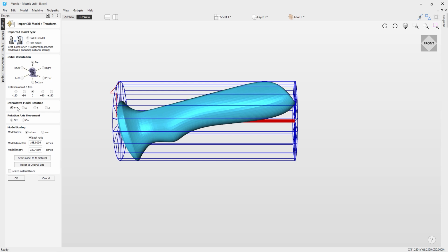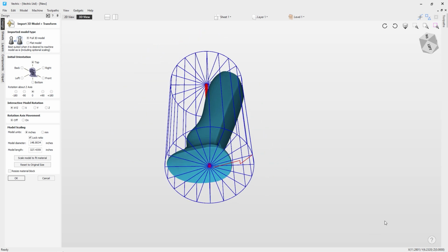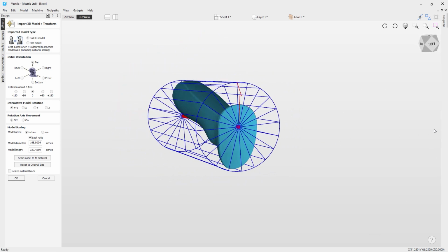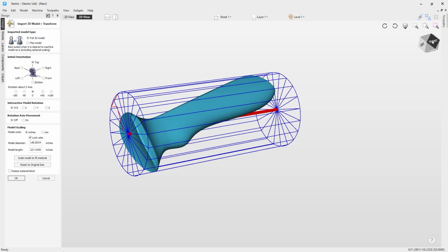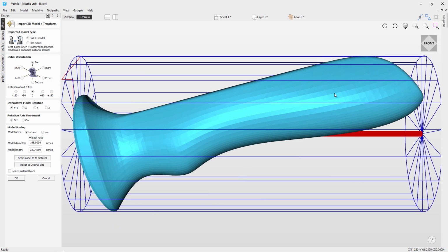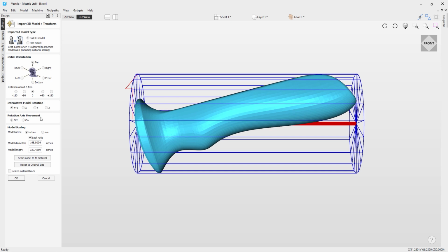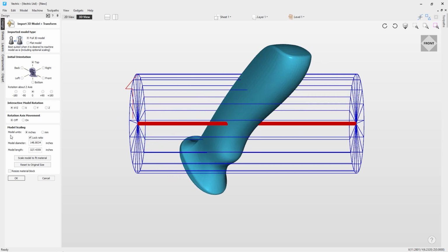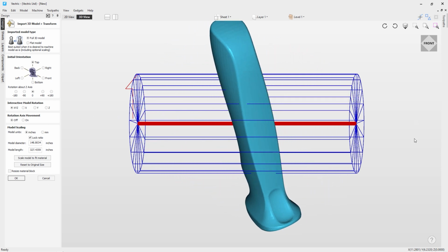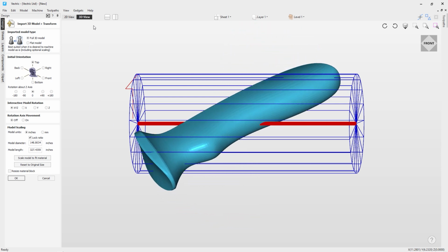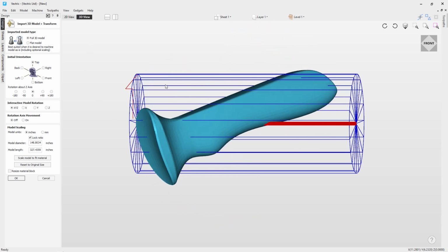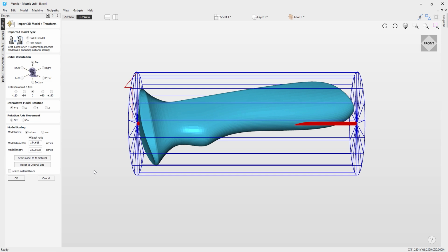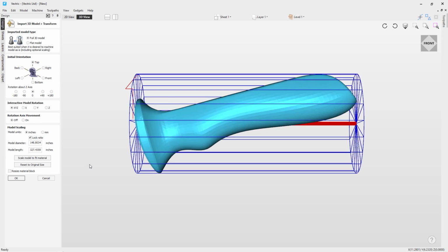Now, it's currently set to XYZ. If I come over to the 3D view here and I right mouse click, I can drag around the cylinder, I can move about and have a look at it in different orientations. Now, if I click on front on the view control over here, we'll go back to the front. But if you notice, if I left mouse click, I can drag this around now freely. So I can move this about freely where I need to place it, and it will respect the new location when I let go of the left mouse click. But I'm just going to Control Z that for now, and we'll have a look at another view.